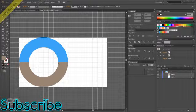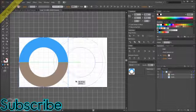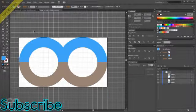So whatever I have created now, I can go ahead and duplicate that onto the side. For duplication, I'll use Alt, click and drag along with Shift so that it intersects over there at the edge, and it's done. I just had to make sure that the X and Y values for transforms are exact. So this is pretty much done.